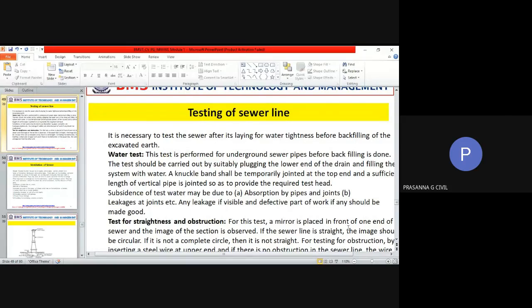The calculated RLs will be there so that you know your bottom should be at this particular RL. Using the boning rod, the correct RL distance will be measured so that the trench bottom can be kept according to that particular RL itself. Once the RLs are all done and the bottom of your trench has been put to the gradient required,